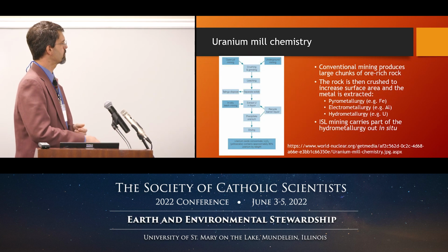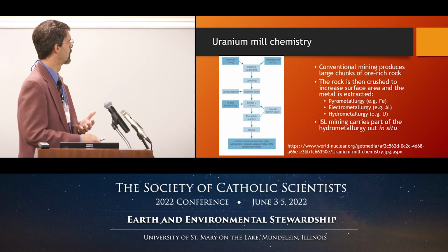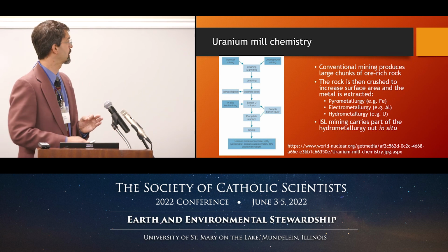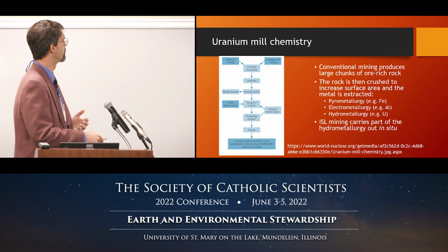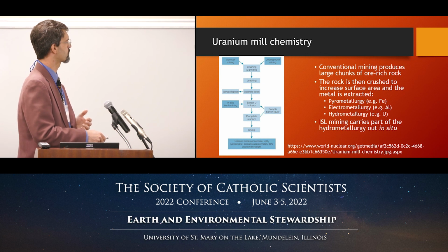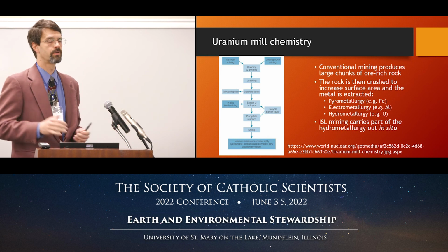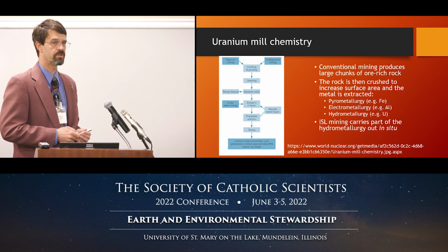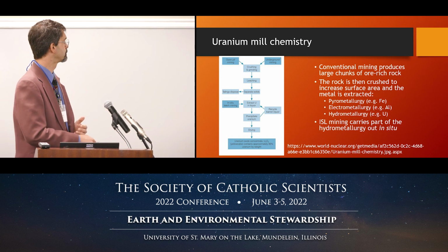And here's a very schematic overview of what happens after you've mined the uranium. In the in situ leaching, you get to skip the whole top of this diagram, and that's a great thing, because up here, I have used my equipment, I've burnt carbon, to haul the stuff out of the ground. I've crushed it, I've ground it, and I've leached it. And whatever I leach it with, which is true for metals across the board, most hydrometallurgic processes depend on really unpleasant chemicals. So we'll talk about one of those examples in a second, but strong acids, things like that.